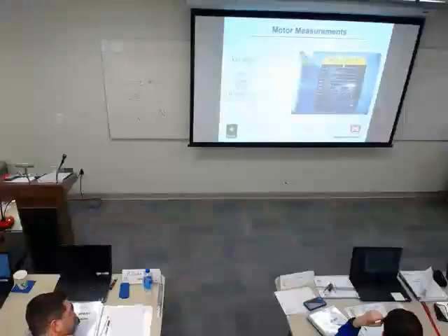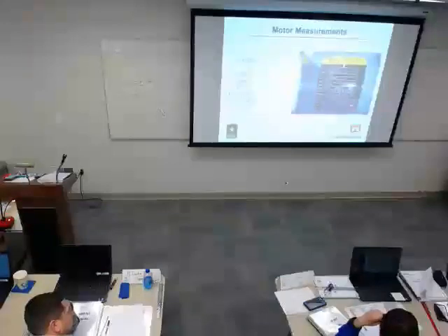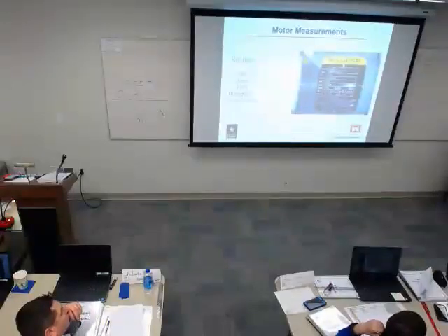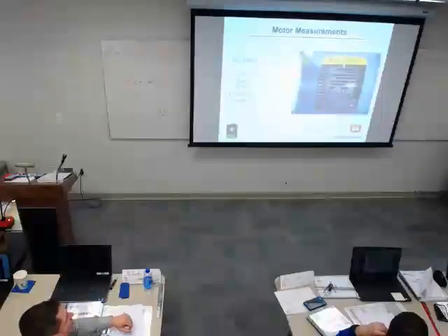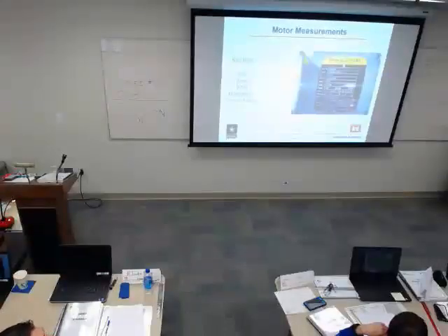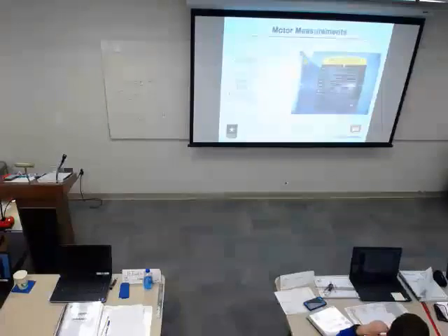They're going to measure on a 3-phase piece of equipment. You've got 3 legs. He's going to use a clamp-on ammeter and measure each leg individually. You'll get a separate amperage reading on each one of those. So none of those can be over the rated amperage, depending on which voltage you're at. And I don't know what the number is, either 5 or 10%, they also can't be any more than that apart. They won't be exactly the same because your voltage is going to be a little bit different on each leg. But yes, the TAB standard does cover how different each one of those can be.